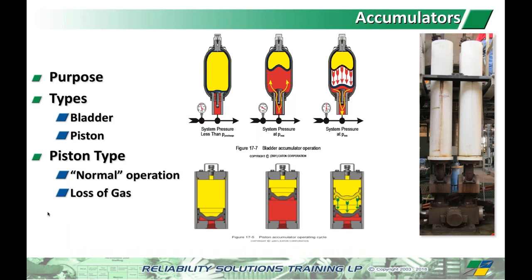Right there where you've got that crackling, that's where it's starting to feather. So a relief valve should either be open or closed. And so if you come up on one that's got that crackling, then it's feathering for some reason, or is it leaking? Okay, combine that with an infrared and look for heat. You might find out where your flow is going, so your machine is not going.